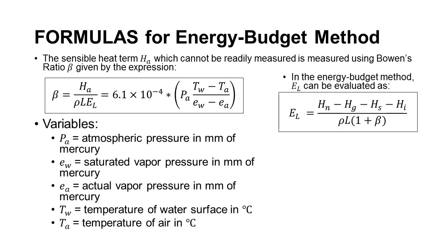So as we can see here, the estimation of evaporation in a lake by the energy balance method has been found to give satisfactory results, with errors of the order of 5% when applied to periods less than a week. Further details of the energy budget method are available in some references, but in this situation, I think you understand how the formula should go.